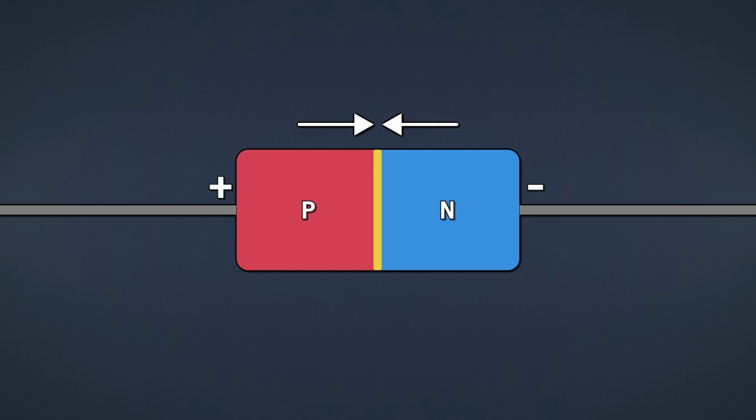As you can see, semiconductive substrates can be used to build electronic components. And because it all depends on the properties of atoms, we can make these components insanely small. So how does a transistor work? Let's take a p-type material and put some n-type over here and here, then add 2 pins into them.